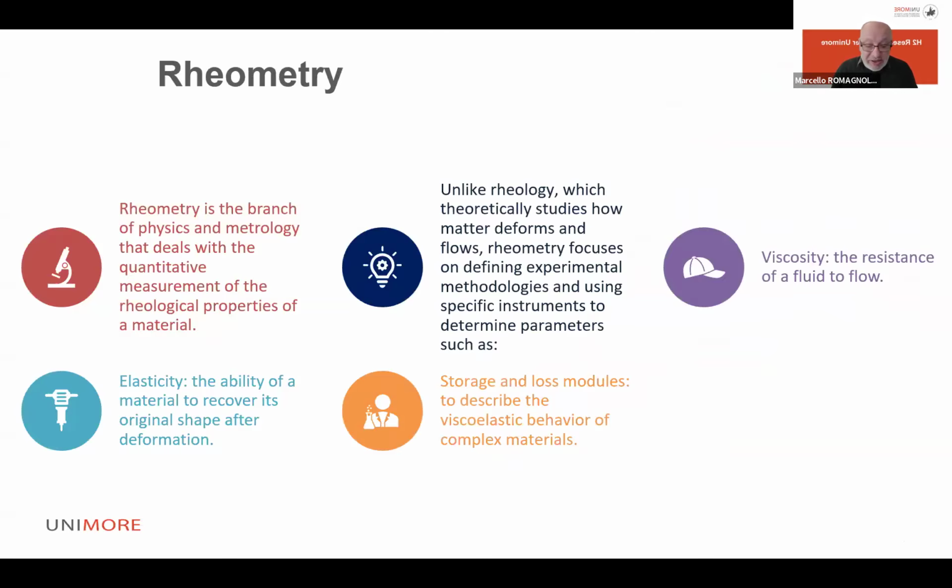So rheometry is the part of the rheology science that deals with how to make the measurements necessary to develop models. While rheology tells us why a material flows, rheometry defines the experimental procedure, that in rheology is very, very important, because if we change the procedure to measure the rheological behavior, we can change also the response of the material.